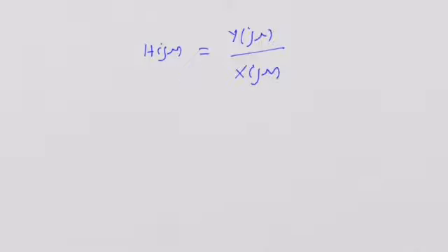The transfer function of a complicated system is actually determined by using frequency response tests only. The design and parameter adjustment of the circuits are all carried out in the frequency domain, especially by looking at the frequency response characteristics.